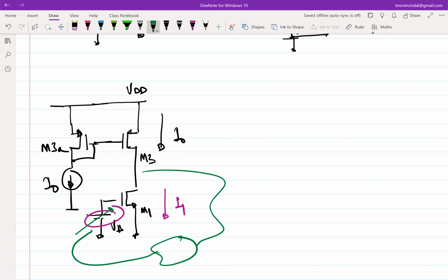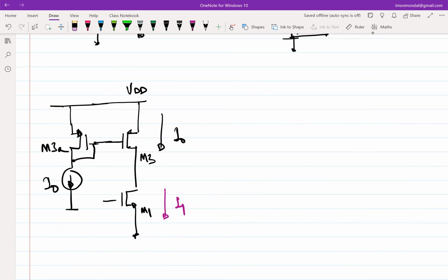So if I assume at the back of the mind that there is negative feedback which is keeping the bias constant, I can say that I will analyze this in an open loop fashion, which means that maybe I have applied my input here, and I will try to figure out the gain between V0 and Vi. So what will be the gain between V0 and Vi in this case? Now, obviously, if you neglect GDS of M1 and M3, what will be the incremental gain?